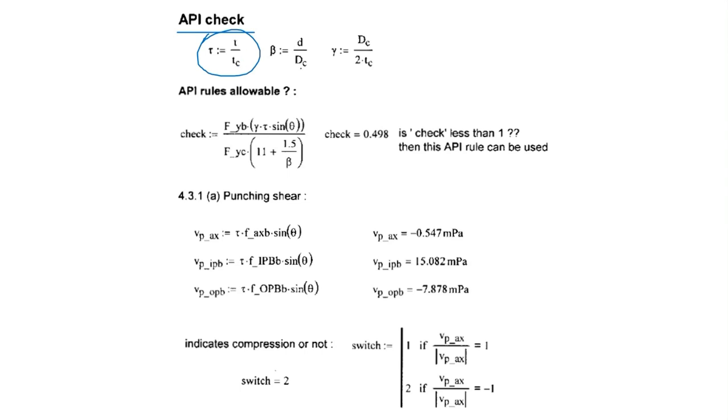Beta is diameter of brace by diameter of can. Gamma is diameter of can by 2 times thickness of can. We can define all this, and we can come to know the UC ratio. From this, the A factor parameter we have seen, right? The QF factor, Q in plane, out of plane factor, all these values we can put in the Excel sheet also. We can do it.